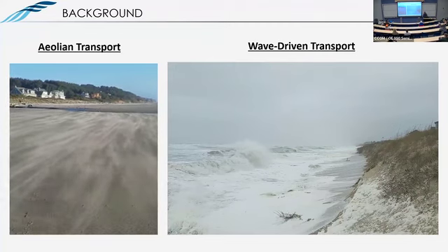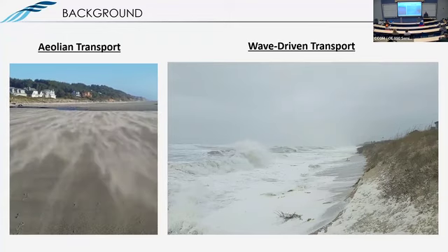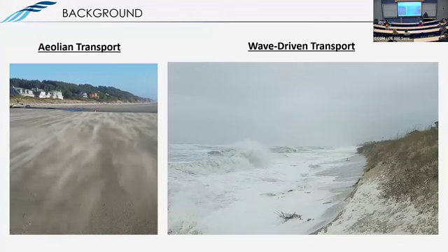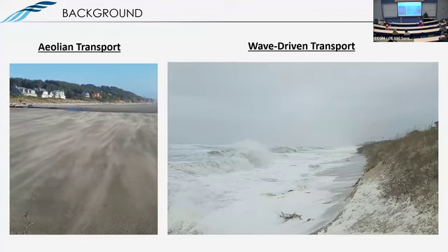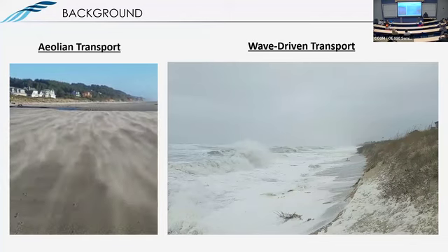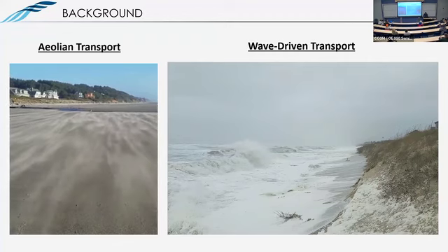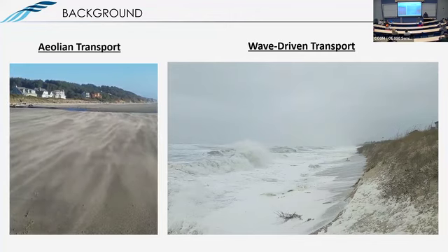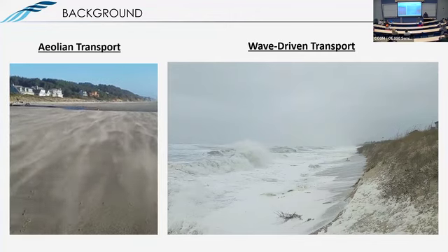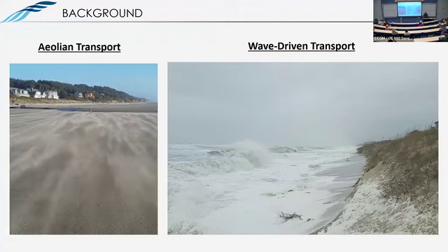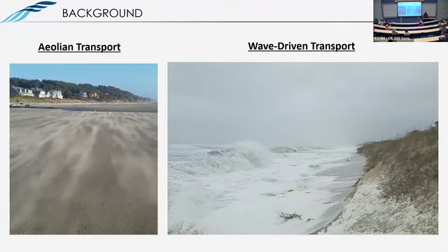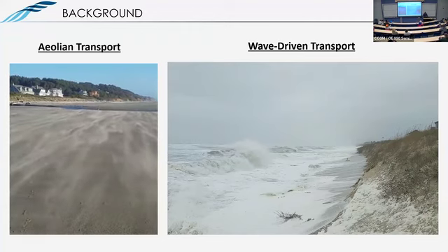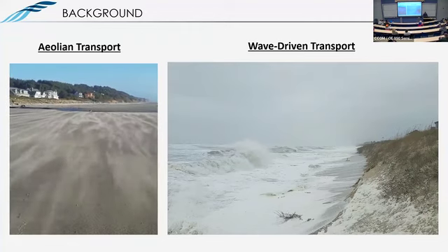Yeah, thanks. Nick, I think you suggested, and it makes sense, that the saltation height is correlated to the boundary layer thickness. And the magnitude of saltation is going to be correlated to, I suspect, what you call U threshold, the wind speed needed to mobilize the sediment. I can imagine, though, that that is a function of moisture of the bed. So when the beach is dry, you're going to see more aeolian transport. Can you comment on that? Because for places like macrotidal beaches, that's going to really matter.